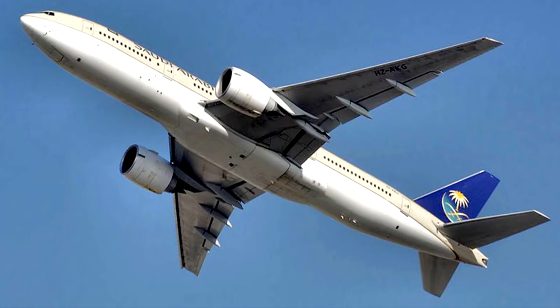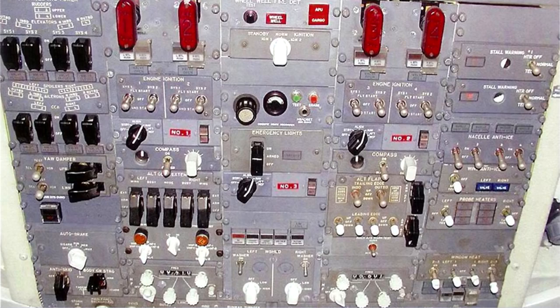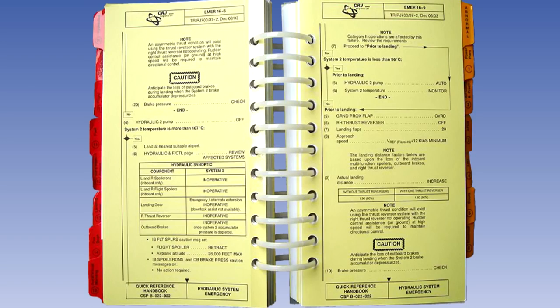Systems are tested for proven reliability, so that multiple independent failures are unlikely to occur on the same flight. Airlines using large twin-engined aeroplanes for extended range operations have to continually monitor and prove their engine reliability in order to be allowed to operate. Failure warning systems are provided for the crew to be made aware of such failures. Flight crew procedures are developed to limit the effect of any failure.